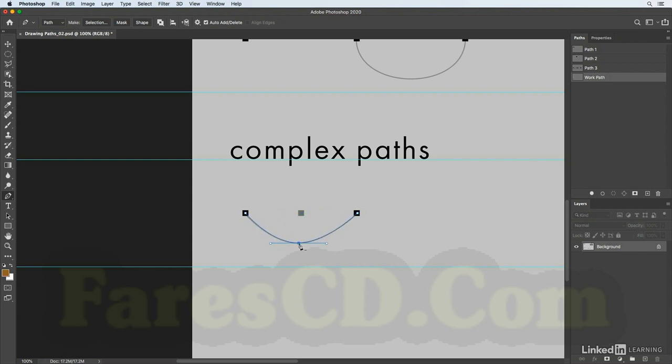Now if I want to turn this into a corner point, I can switch tools and select the Corner Point tool, and then click on the anchor point. With the Corner Point tool still selected, I can click and drag out in order to convert it back to a curved point. But I can also do that without leaving the pen tool.